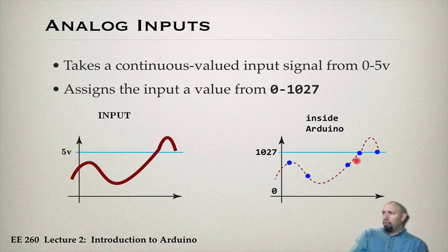But hopefully you have enough data for it to be useful. And so we have issues, the issue of what's called aliasing that can arise when you sample. Aliasing is when you have a signal with certain frequencies, and if you have frequencies that are too high for your sampling, then one frequency can appear to be another, and that's always an interesting phenomenon. So analog inputs are an important consideration.